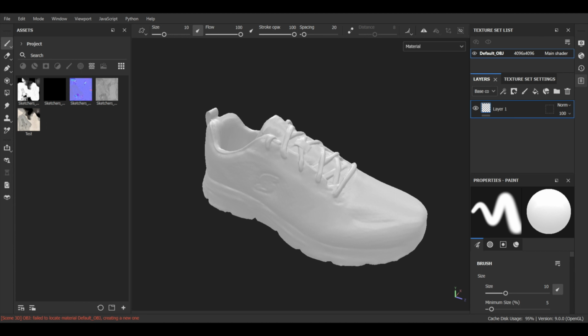The reason why we do this is because typically when you get an asset out of Artec, it's about 2 to 3 million polygons. And that's just far too much geometry to display on a website or on a mobile device where a lot of these products will be shown. So if you're looking to put 3D models in a storefront, you need to make sure that your 3D assets are somewhere between the range of 50,000 polygons to 100,000 polygons. And that translates roughly to 5 megabytes to 10 megabytes. Anything beyond that is just too heavy to put multiples on a web page.